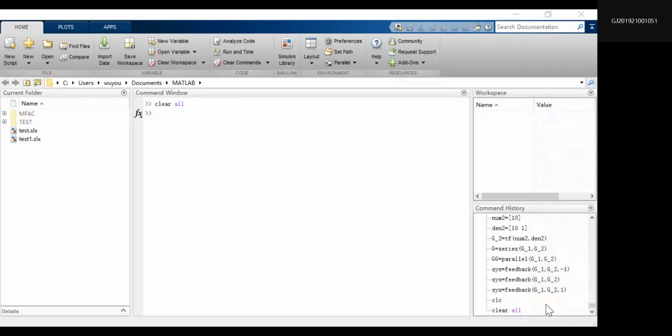And then what's the next connection? First, we have two transfer functions here, and then we have the summing point already. And if you want to see the output, you need to use one type of block, maybe scope, maybe display. If you don't use one of those, how can you read the output?